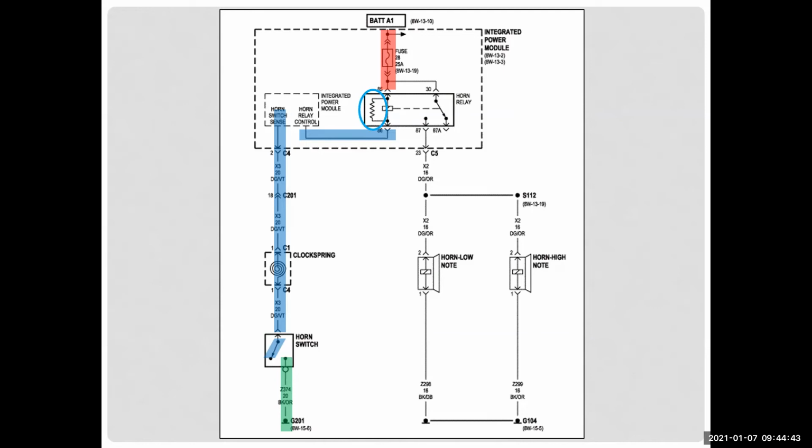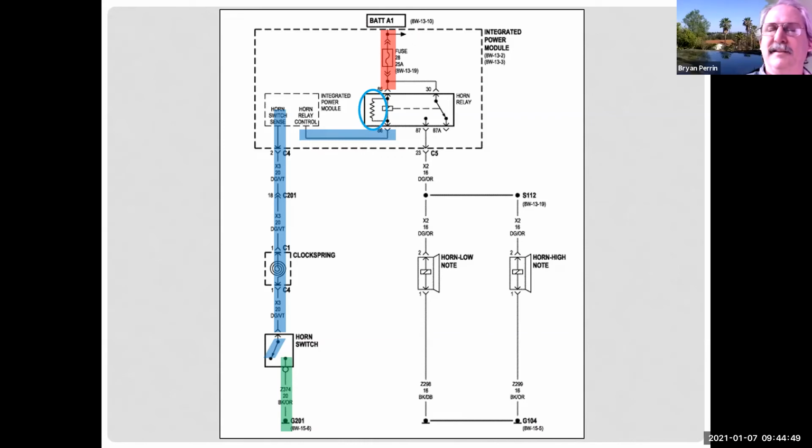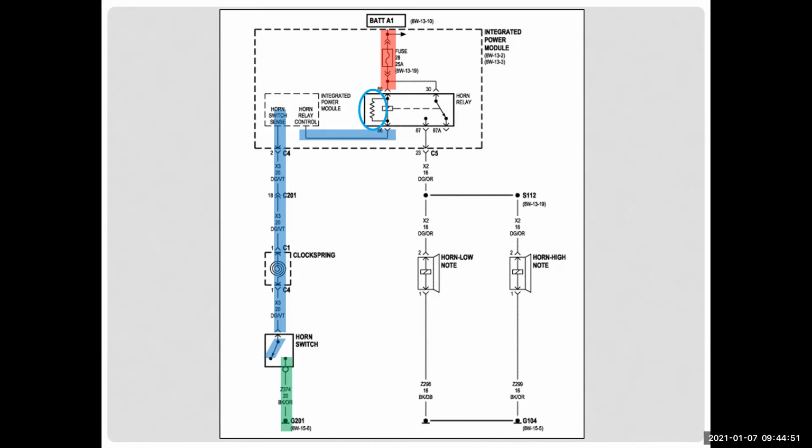And usually when you have multiple issues happening, it all probably stems from the same root cause. And by monitoring and going through similar schematics like you have here, he actually finds a bad ground usually or something, because that may be a common point for multiple components, and he fixes the whole thing by doing it.